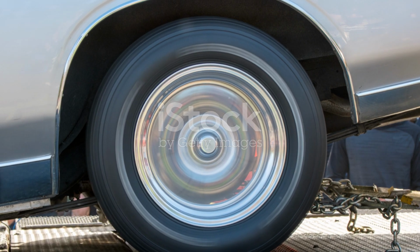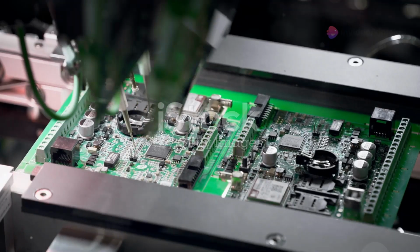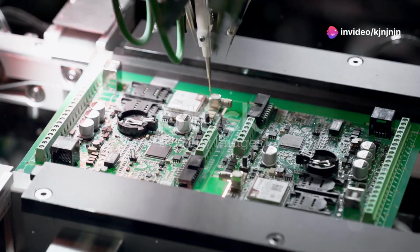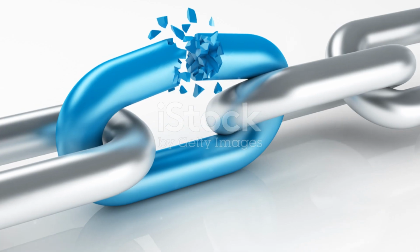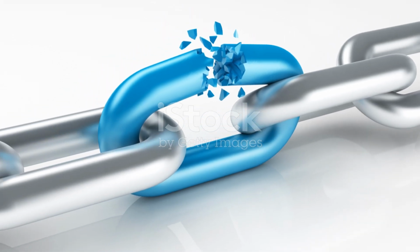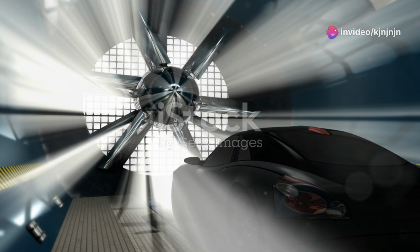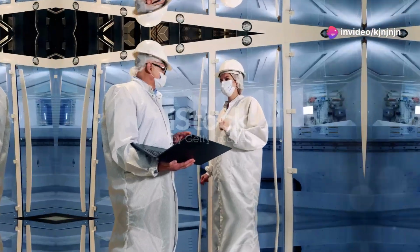Fatigue tests assess a material's resistance to failure under cyclic loading. The specimen is subjected to repeated cycles of stress, and the number of cycles to failure is recorded. Fatigue failure can occur at stress levels significantly lower than the material's ultimate tensile strength. Fatigue tests are crucial for designing components that experience cyclic loading, such as aircraft wings and automotive parts.